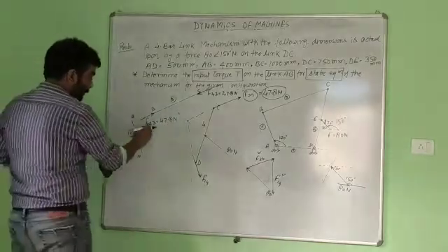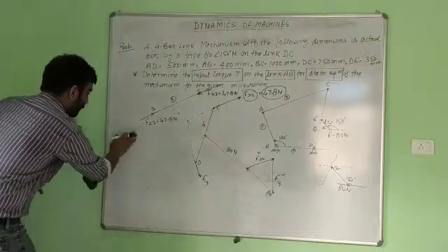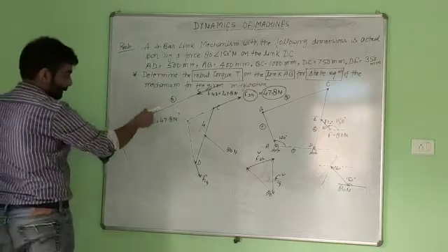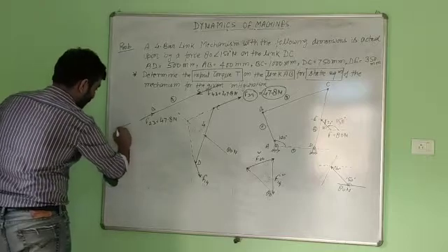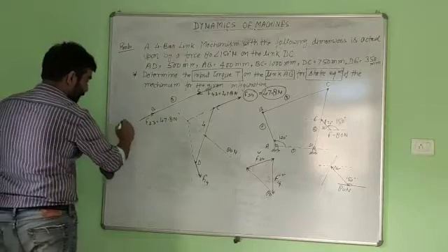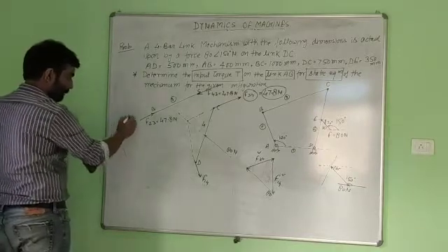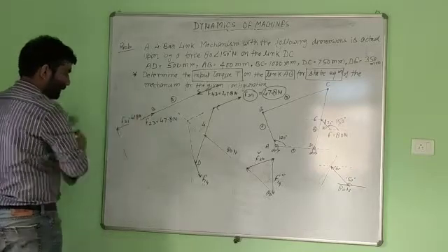Now we have member 1 here. If this force is acting in this direction, then on member 1 we will have one opposite force, F32, by member 3 on member 2, of equal magnitude 47.8 Newton acting here.